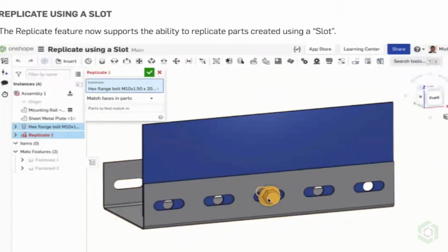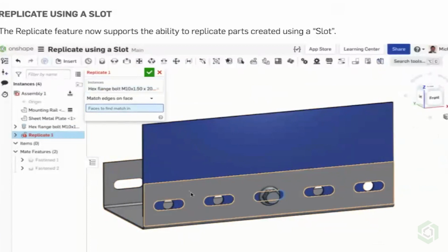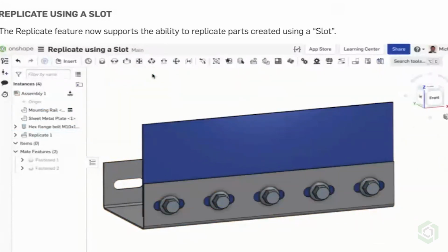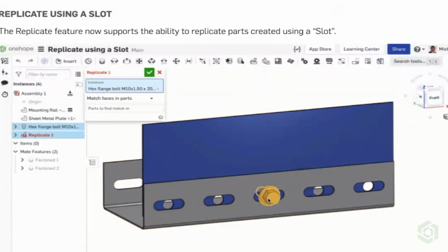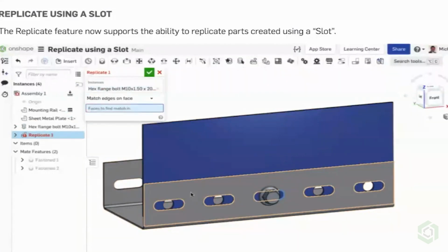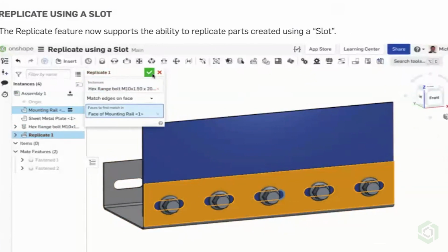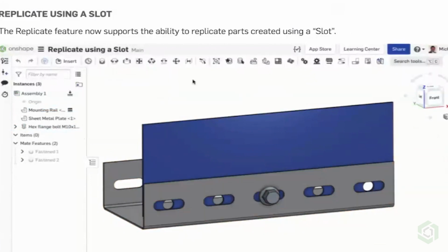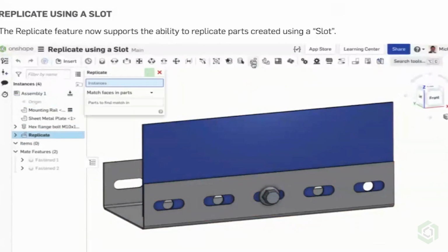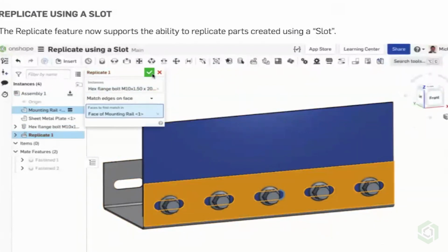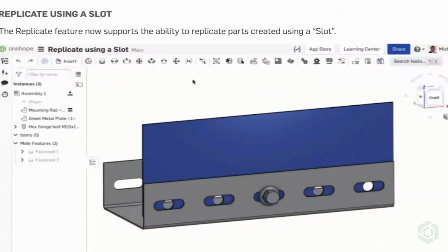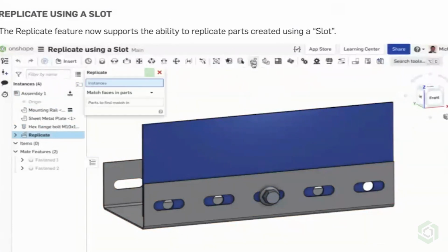Yeah, just to spend a few more seconds on parametric replicate, since that was released before we had our podcast as a thing. Parametric replicate is really amazing. The way we do replicate in Onshape is very different than how you would do a feature-based pattern in a different CAD system, right? If you do a parametric pattern at the assembly level in CAD System X, you need to know that there was a pattern that underlies that in the original part that was brought in, right? However, with Onshape, we're doing it in a geometry-based way versus a feature-based way, right?